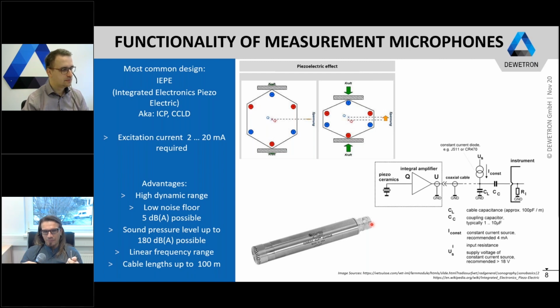As little as possible. And concert microphones also use a different type of transducer. They don't have an IEPE transducer, but for example a dynamic transducer, which means that you have a coil which is wrapped around a magnet. As soon as the sound wave hits the membrane, the coil will start to move across the magnet, and then you induce a voltage which is proportional to your sound pressure again.